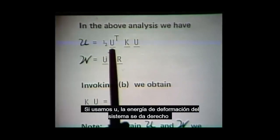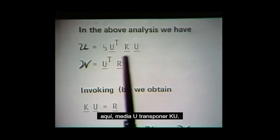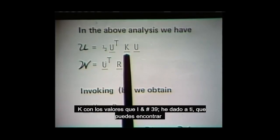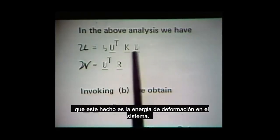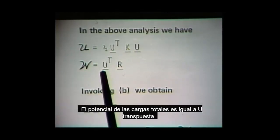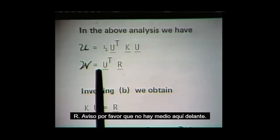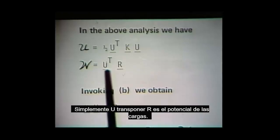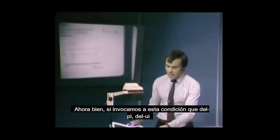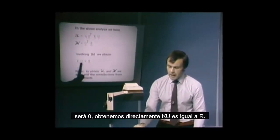the strain energy of the system is given right here. 1/2 U transpose Ku. If you were to multiply this out, substituting for U and for K the values that I've given to you, you would find that this indeed is the strain energy in the system. The potential of the total loads is given by U transposed R. Notice please that there is no 1/2 here in front. Simply U transposed R is the potential of the loads. Now if we invoke this condition that del pi del ui shall be 0, we directly obtain Ku equals R.